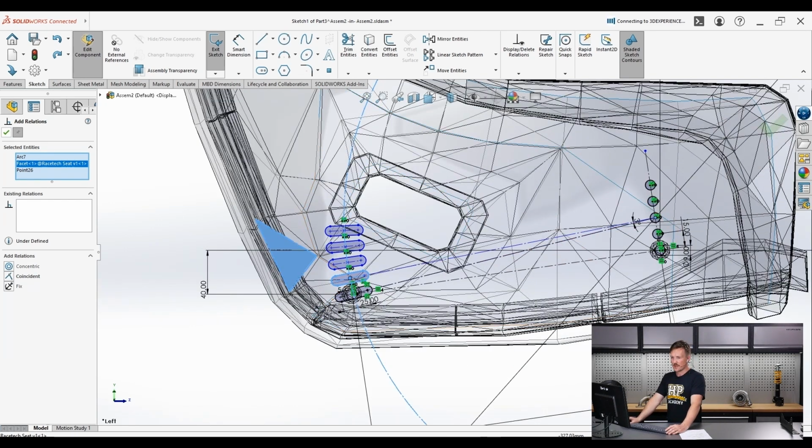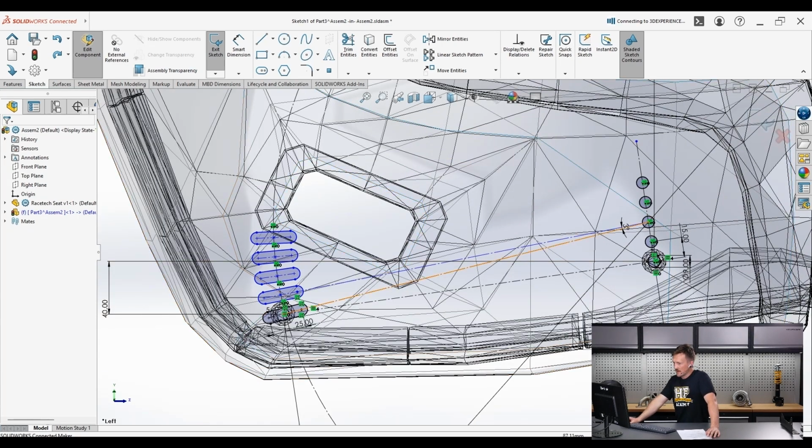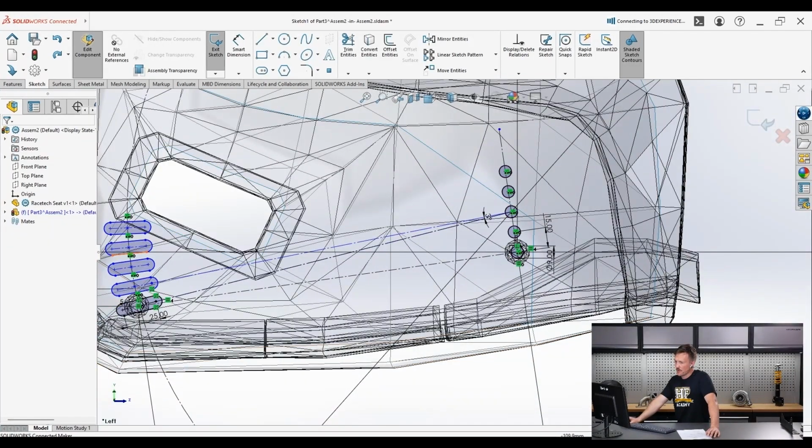And the little check that I was talking about before to understand if the spacing is going to be correct, we'll just do that now. So basically, we know that the distance between the center hole and any of these is going to be perfect. So if we moved the seat between any of these, and the front was mounted in the center hole and we moved the rear mount between any of these different slots, we know it's going to be correct because the spacing between the holes is at 278 measurement, and that is the radius of this arc here.